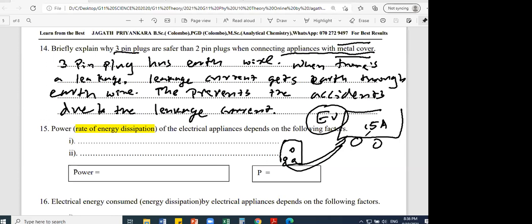It does not allow charging using only a 2-pin plug. So definitely you must have an earth wire, for safety, because the entire vehicle body is metal. What happens when there's a small leakage of current from the battery to the metal body or outer covering? Then you get electrocuted. That is very risky. So earth wire is very, very important.